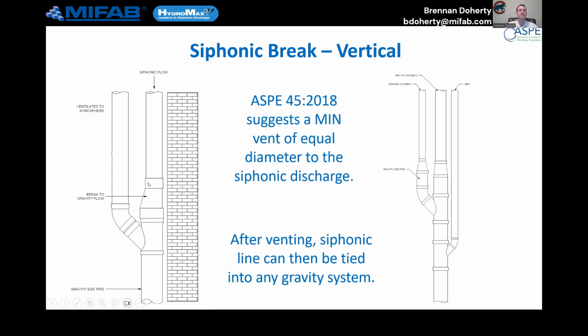Another way I've seen this used very well: I have a warehouse client that doesn't want to put an area drain 5 feet outside of their building. So they take that siphonic action all the way to the ground. They punch that vent out the sidewall where they then hide it behind some shrubs, at which point they've gotten their maximum siphonic savings and they're achieving code approval.